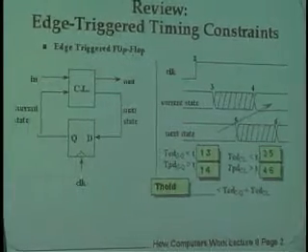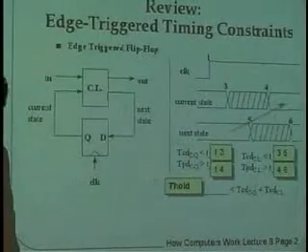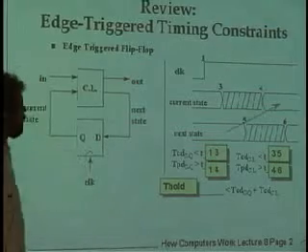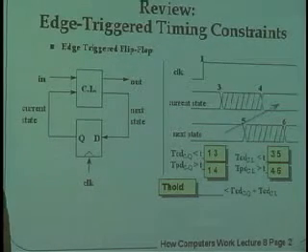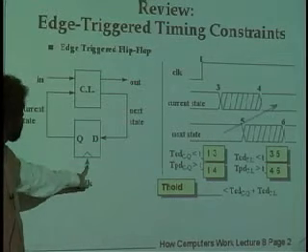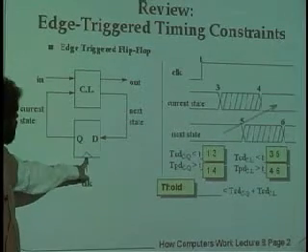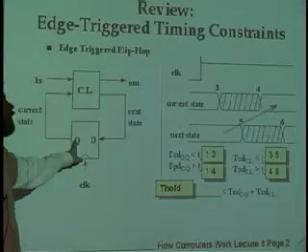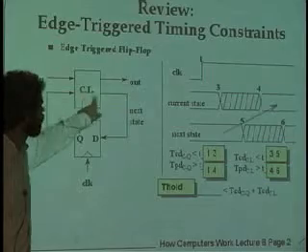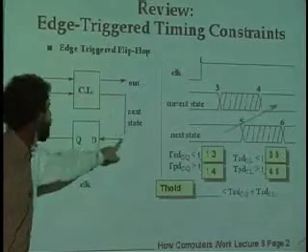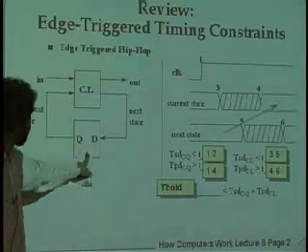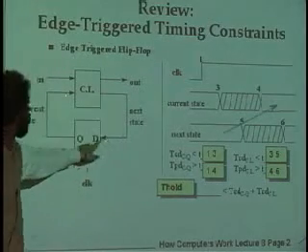And if you remember, there were certain constraints on the timing having to do with this feedback loop right here. And the first constraint was one saying whether or not the loop would work at all. It was a question of, as soon as this clock goes off, then contamination begins to affect this Q output here. And as soon as this gets contaminated, then contamination flows through the combinational logic and comes back around here.